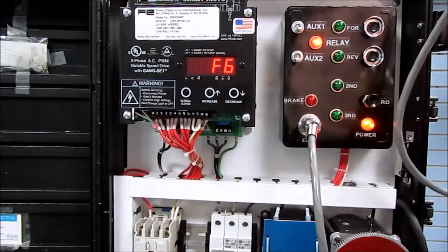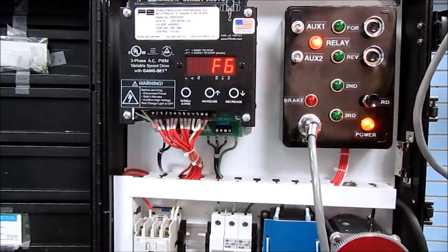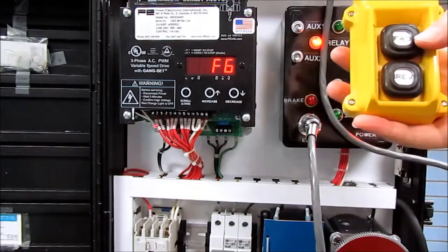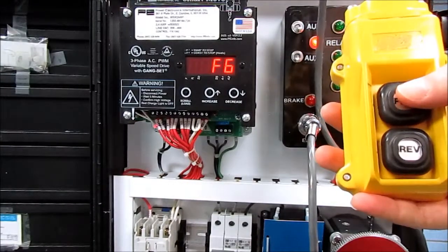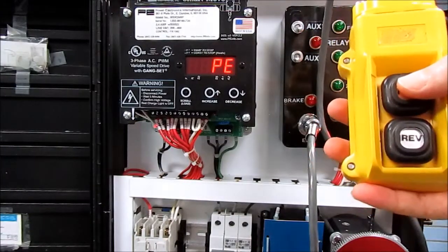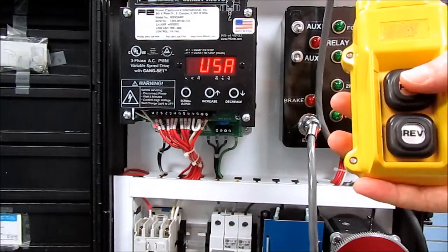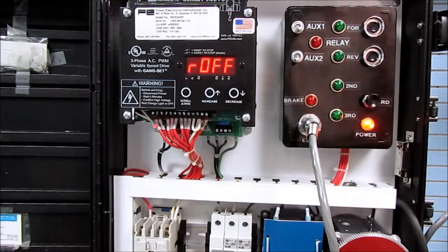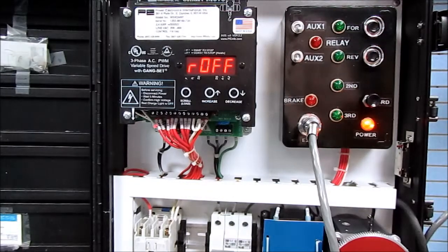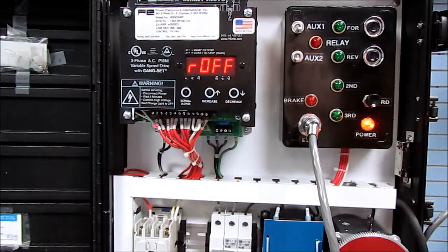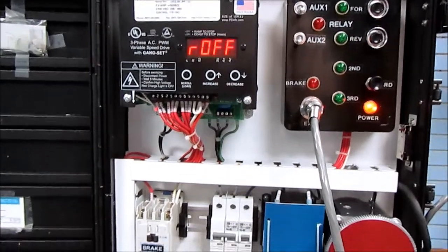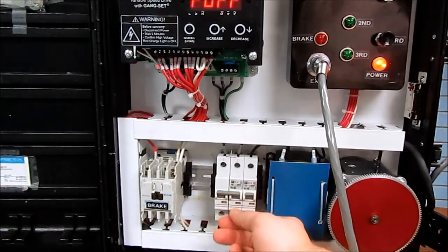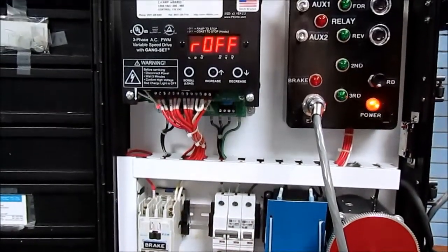For nearly all of the event codes you can see on the display, the default way to clear this code is by simply toggling your control input by quickly depressing and releasing either one of your direction buttons twice. After the drive receives this signal, it will reset and then return to the idle screen. The drive will automatically store the event code in one of its memory locations, but notice the code has now been cleared and you are back to the off screen. You may also clear the event code on the unit by turning your line voltage to the drive off and then back on.